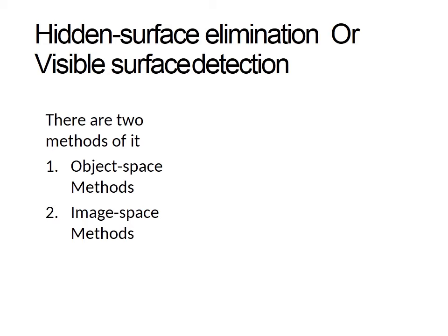These methods generally decide the visible surface in the wireframe model, and are used to determine a visible line. So these algorithms are line based instead of surface based. The method proceeds by determination of parts of an object whose view is obstructed by another object and draws these parts in the same color.